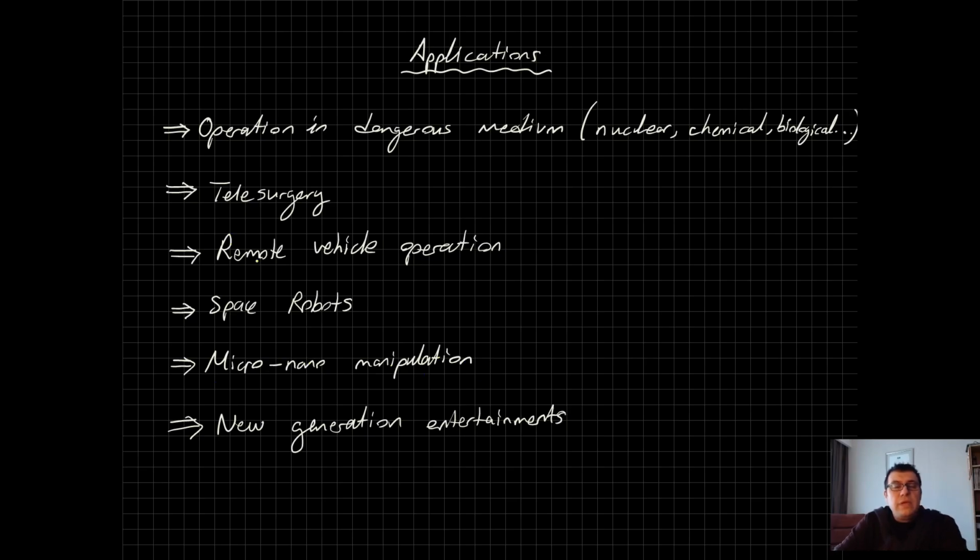For remote vehicle operation, you might need to understand forces on the scale of hundreds of kilograms, but if you use a system on the master side that gives forces equal to hundreds of kilograms, you will not have safety there. So, in order to have this operation, you have to have a small scale on the master side and a big scale on the slave side, right?